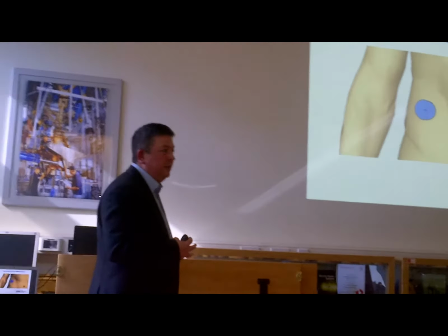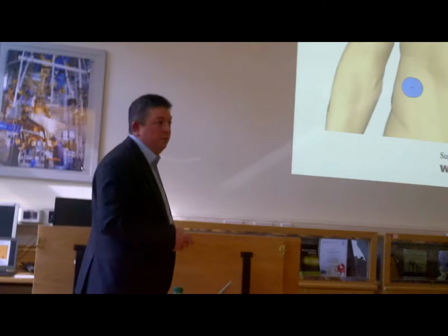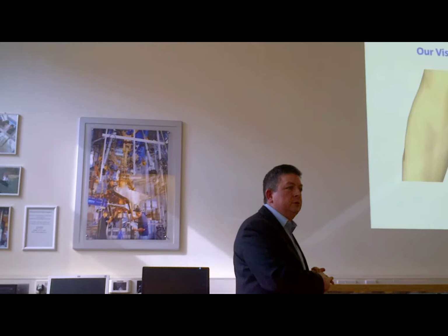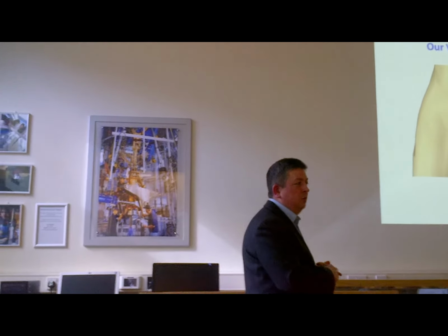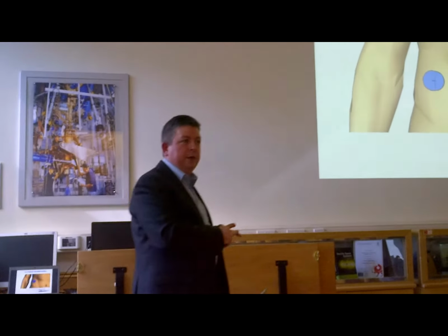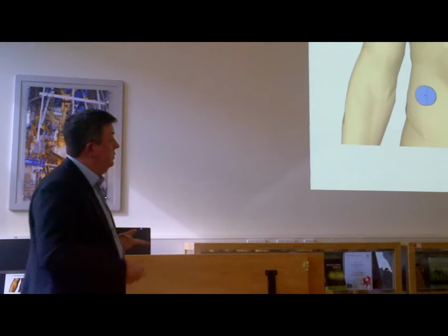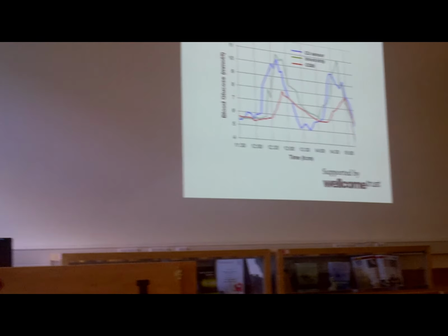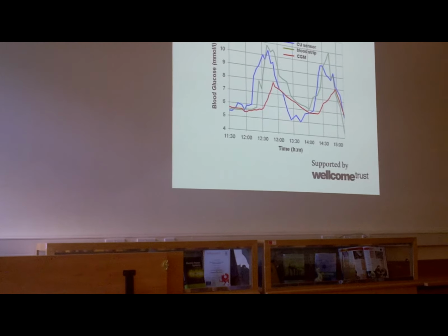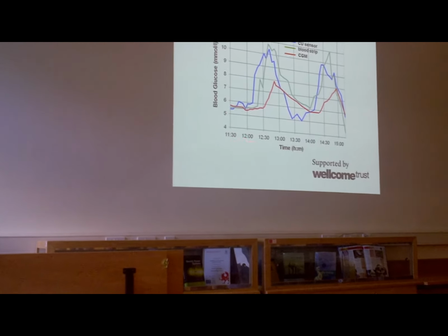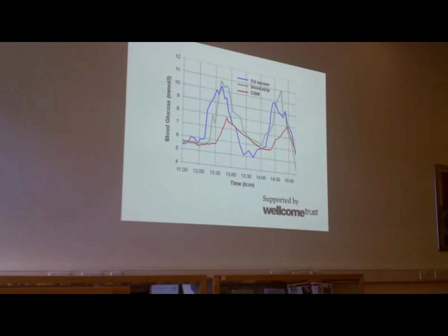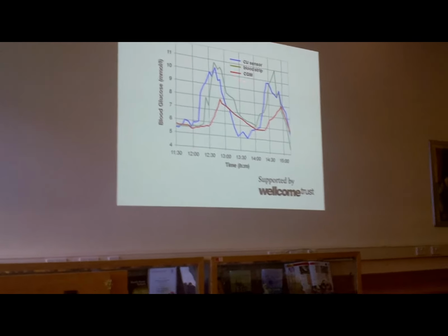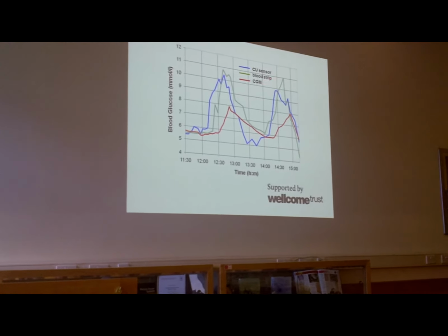It's actually wired up at the moment, but what we hope to do is to develop a little microwave sensor like that that sits on the body, onto which we attach the appropriate medical electronics, and in there will be a transmitter that transmits to a data logger, and hence we measure non-invasively the blood glucose content in blood using these microwave resonator techniques. I should say that this is probably the hardest problem that we're trying to tackle using this type of technology, and it's fraught with difficulty.